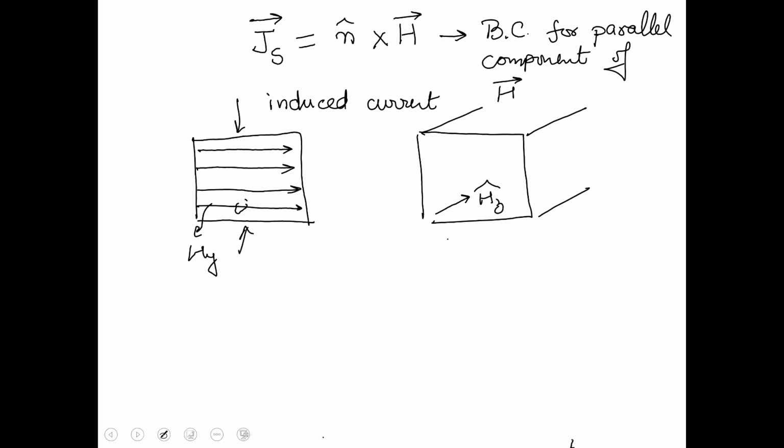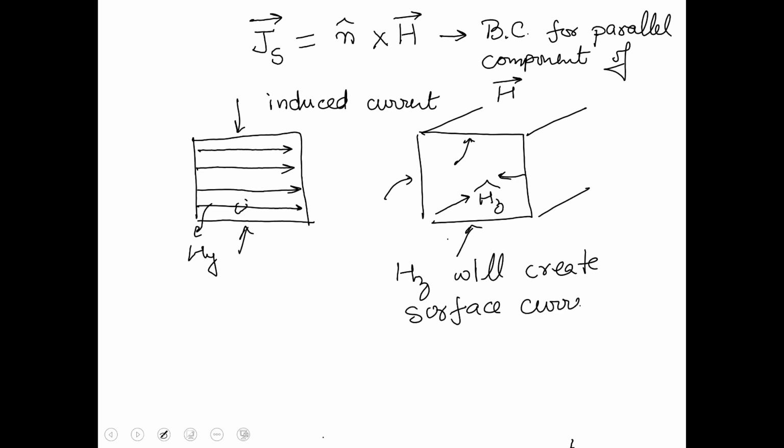This HZ component is going to create, is parallel to all four electric fields. This HZ component is going to create induced currents in all these four planes. HZ will create surface currents in all four planes.